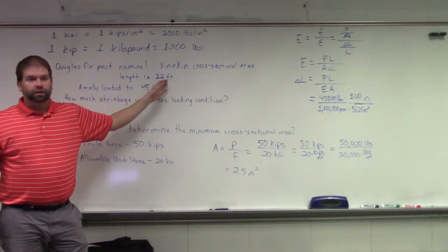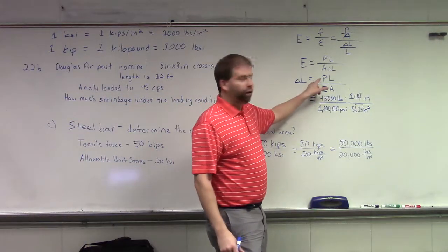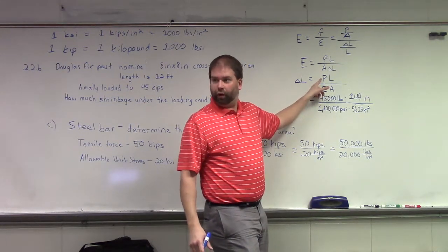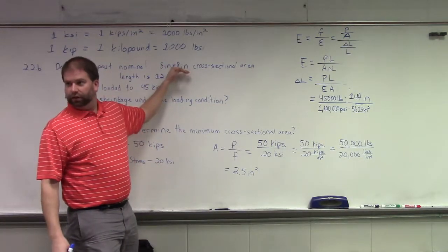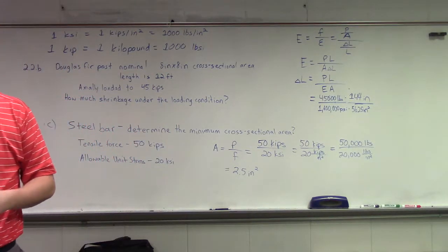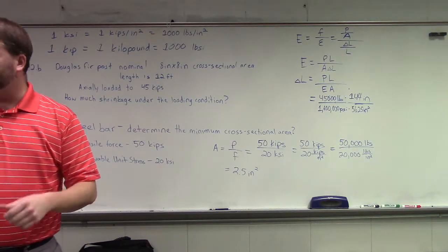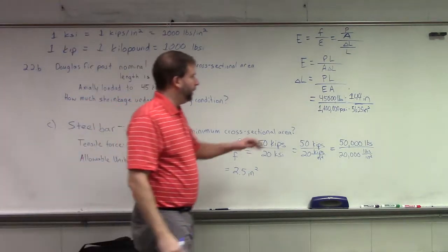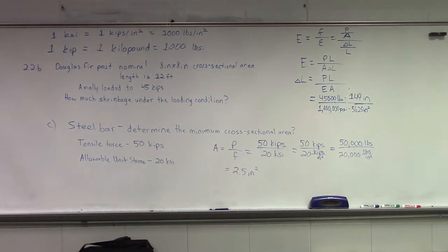Typically speaking though, if you're trying to figure out your allowable stress, if you're trying to manipulate it through the force that's being applied, I would recommend always figuring out what your actual is, because now you're dealing with capacity. When we're dealing with sizing, working within an area, we can run both of those calculations and figure out our wiggle room. But when we need to figure out capacity, we always want to make sure that we're calculating to the actual dimensions.